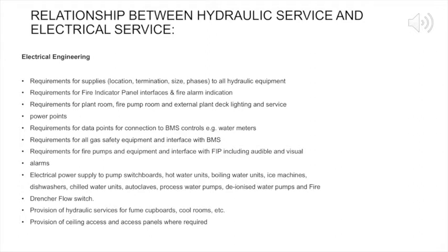So the relationship between hydraulic service and electrical service includes requirements for supplies such as location, termination, size, phases to all hydraulic equipment, requirements for fire indicator panel interfaces and fire alarm indication, requirements for plant room, fire pump room, and external plant deck lighting and service power points, requirements for data points for connection to BMS controls, requirements for all gas safety equipment and interface with BMS, requirements for fire pumps and equipment,